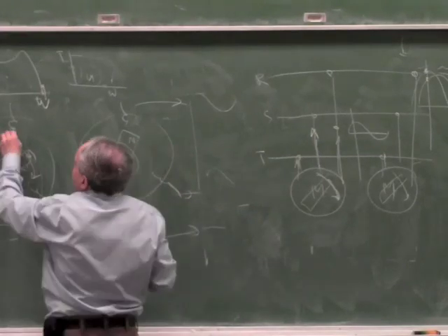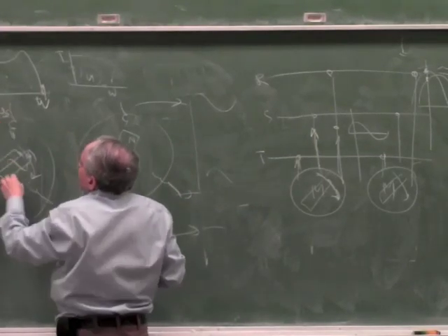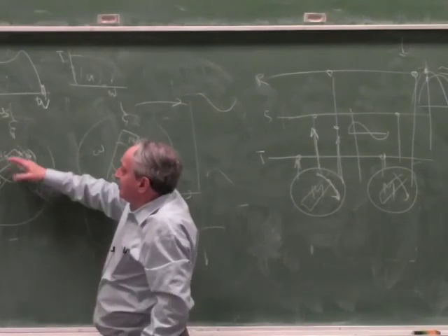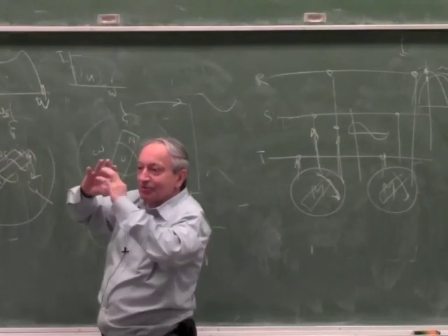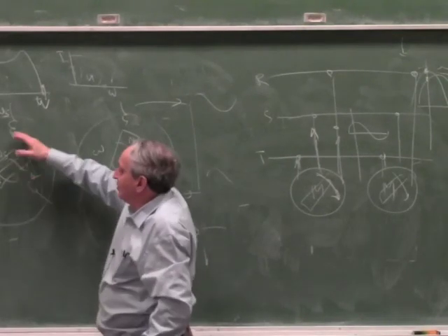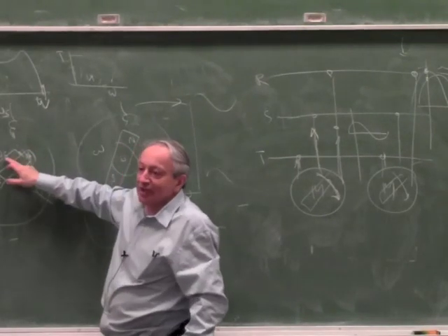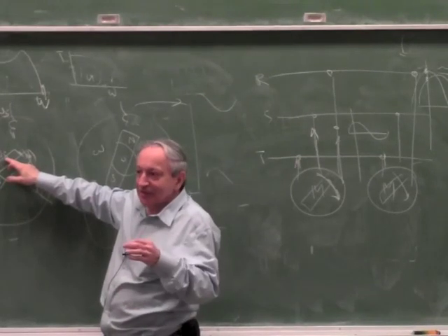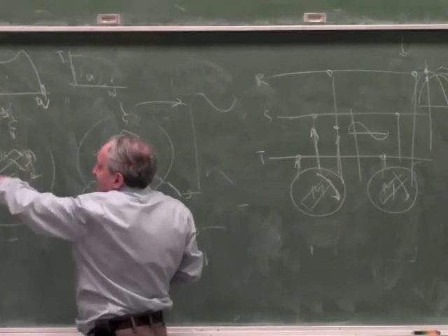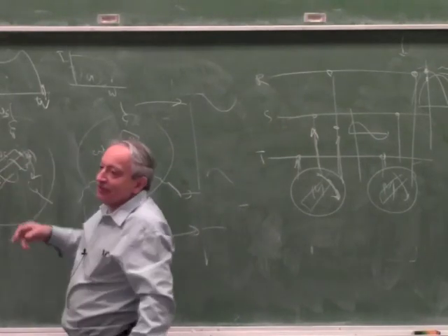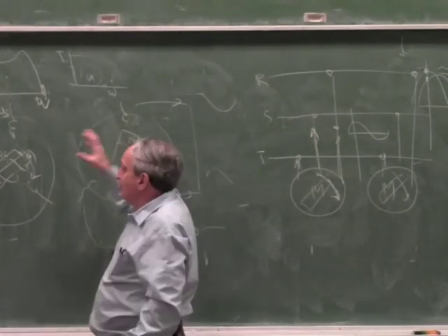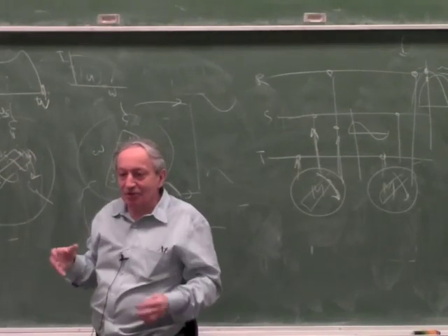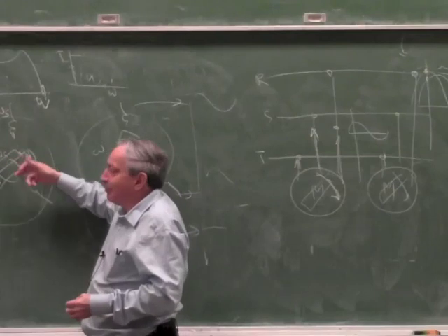If this is omega synchronous and you force this to rotate at omega synchronous, it sees a constant magnetic field, because they're both working together. If it sees a constant magnetic field, there is no induced current, there is no power going into the motor. So the first part is easy to understand. If you force this externally to follow the rotating field, no power will be transferred into the motor, except losses, but actually no power will be coupled to the rotor.